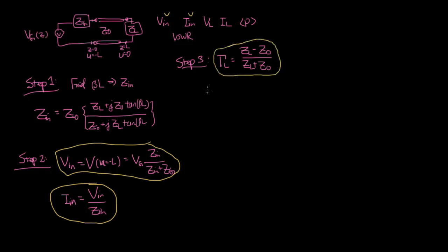And note that since we're going to be multiplying and dividing by gamma L, having this in polar form is pretty useful. So if possible, once you have this, converting it to polar form might be really relevant for the next step, namely to calculate the VSWR.